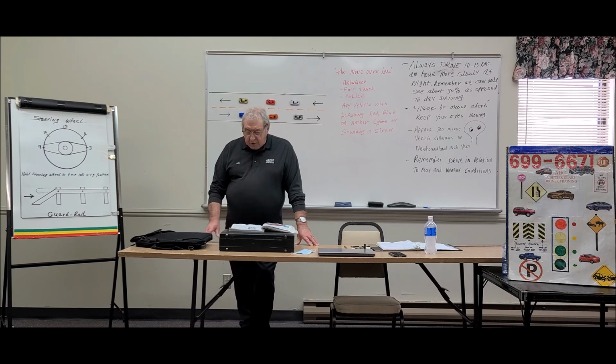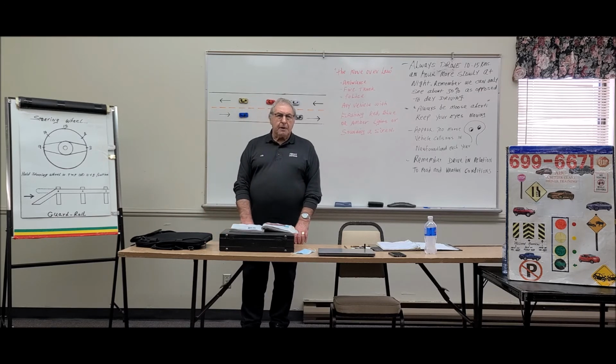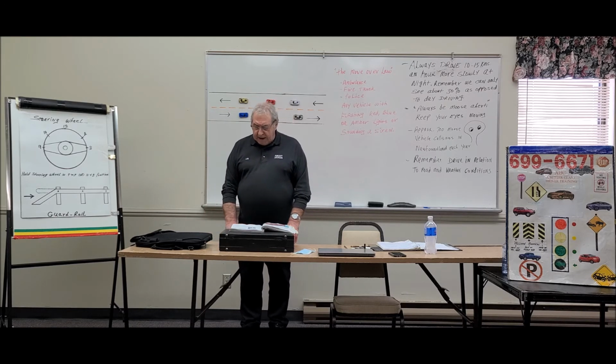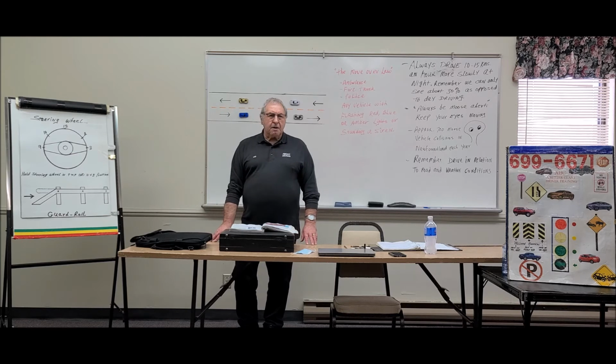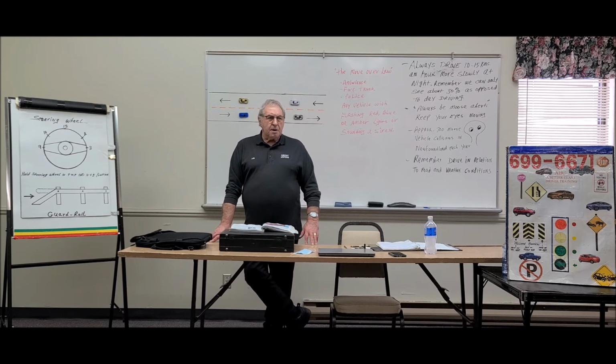So the D there is for drive. When you want to move ahead, you put it in the D position. And 2 and 1 are lower gears that give you more power. You will seldom ever have to use those with an automatic. You know, if you're towing a trailer through heavy snow or mud and not doing over 20 kilometers an hour, you might put it in 2 or 1 for that reason. But other than that, there's never any need of shifting your transmission.